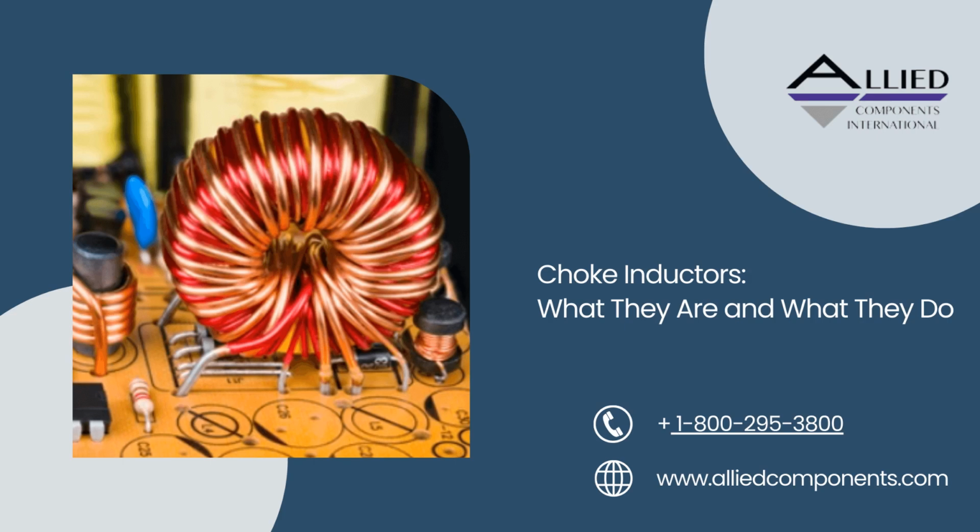Manual operation. In manual choke systems, the operator has to remember to disengage the choke once the engine warms up, or else the engine will run rich, which can lead to poor performance, fouled spark plugs, and wasted fuel.